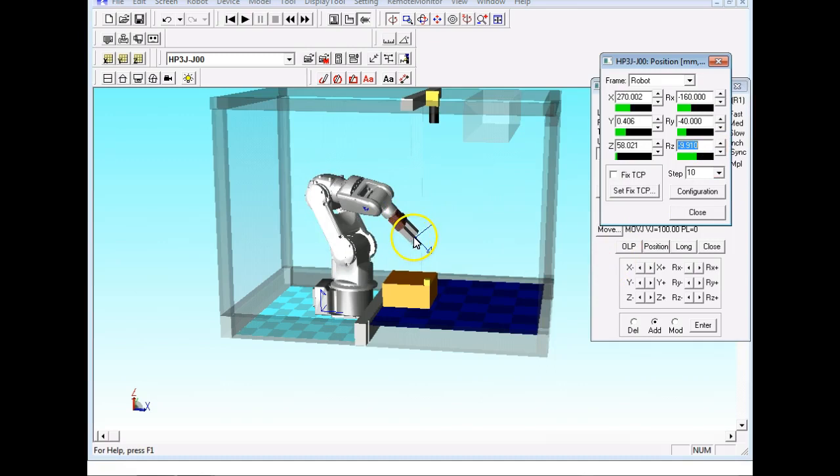And this is moving around something we call a tool center point. So that's what this guy right here is. This is the tool center point. We've already talked about tool center point, right? Yeah. Tool center point is the position that you're trying to go. What's nice about your simulation is you can put this wire diagram up here that shows you the exact location of the tool center point.